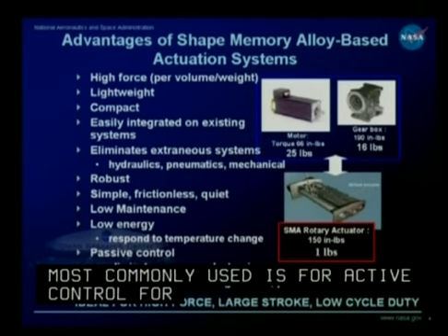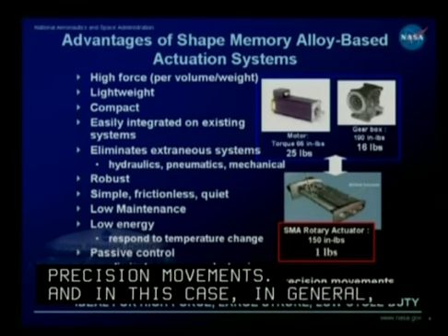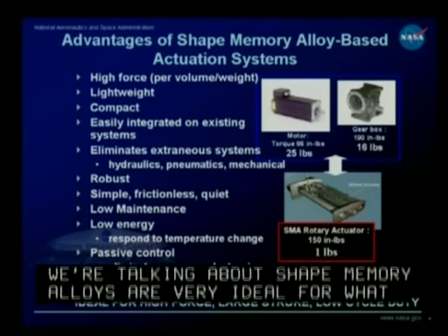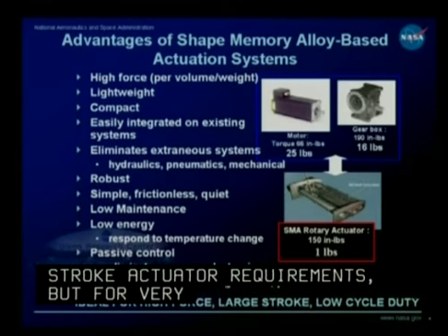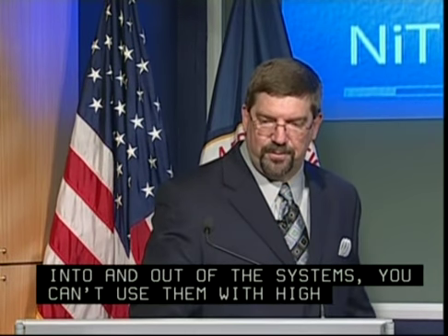In this case, in general, shape memory alloys are very ideal for high force, large stroke actuator requirements, but for very low duty cycle. Because you have to put heat into and out of these systems, you can't use them with a very high frequency, only the frequency at which you can put heat in and out of the system.